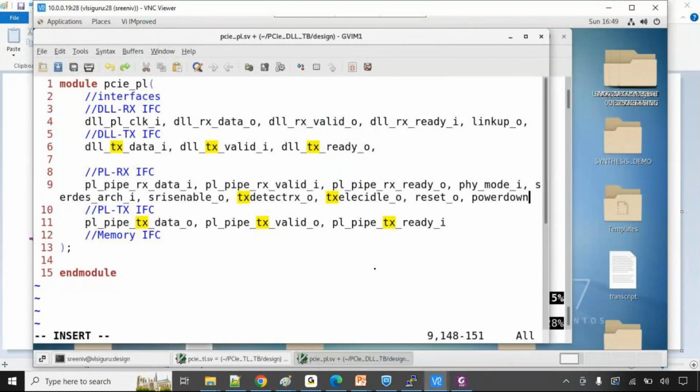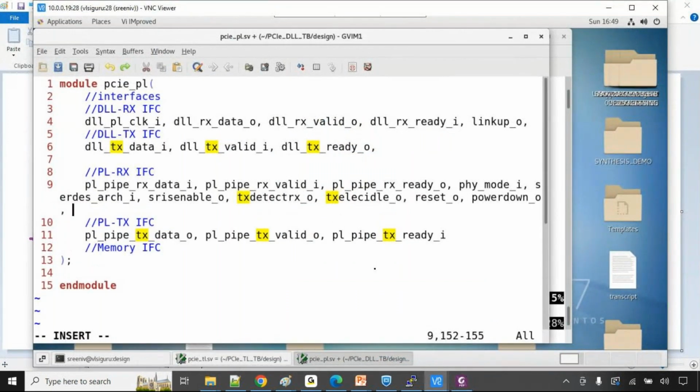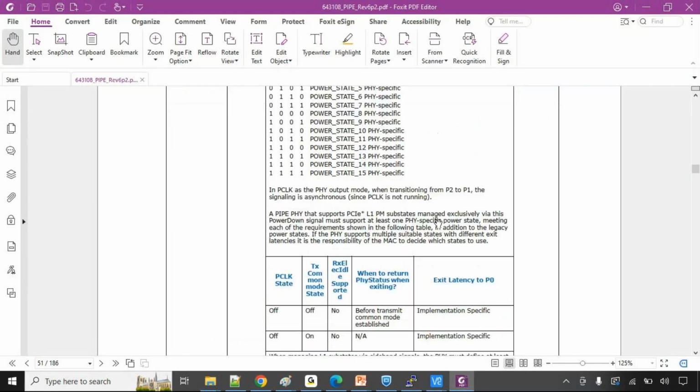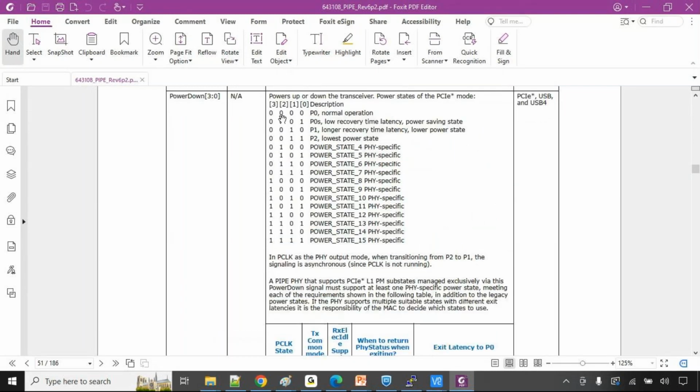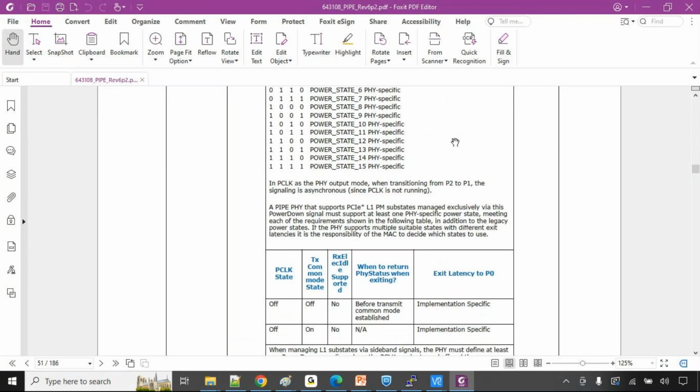The power down indication is given. What we have to do is figure out whether it's input or output. You have to read this. See, it powers down the transmit transceiver or receiver, which means the upper layer is indicating to power down. So that means it's an input to the pipe, meaning output of my physical layer. It's output of MAC and input to the PCS layer. Okay,